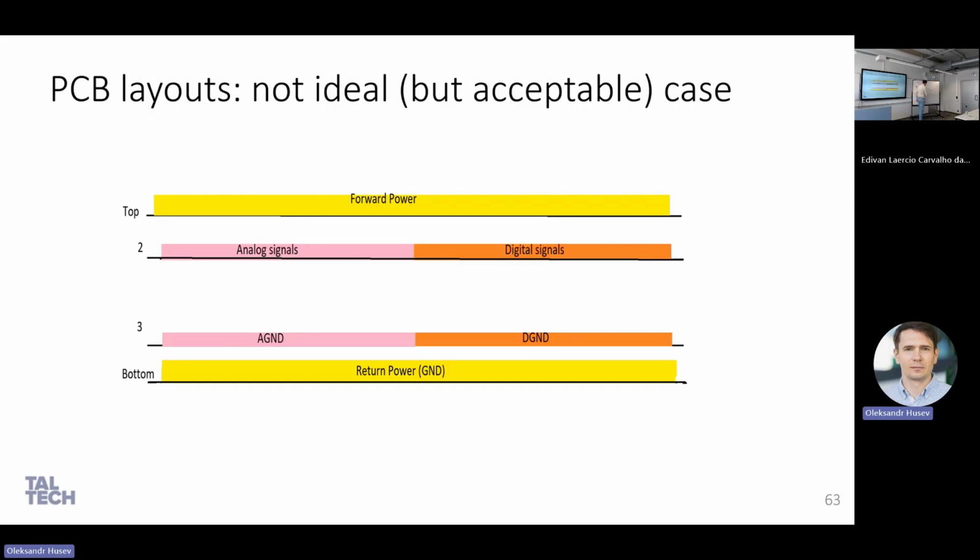It creates a magnetic field. But if you put a capacitor very close to this switch and cell, then from the switching point of view you don't have this conflict between inductors. This capacitor creates a mitigation, it cuts off this inductance impact.